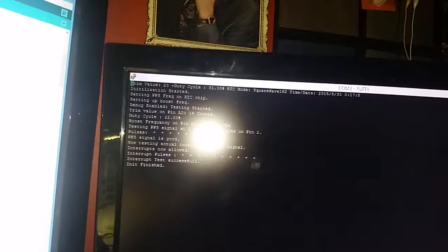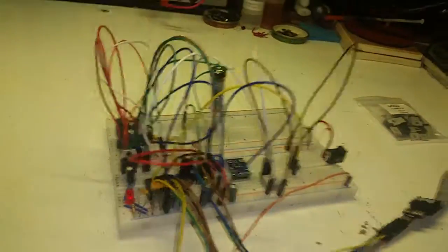So the duty cycle set at 22. I just gotta wait for it to get back to the top, and then you can see the duty cycle will change. I should have hooked up the O-scope so we could see that they were pretty well on as well. But, okay, so duty cycle, if you watch the duty cycle, it'll change. It's kind of hard to see. It's 31, 34, 44. It only goes up to, I think, 70. Yeah, 79. And then we can bring it back down. So, yeah, that's pretty sweet. Anyways, quick little update. Well, not so quick, I guess.